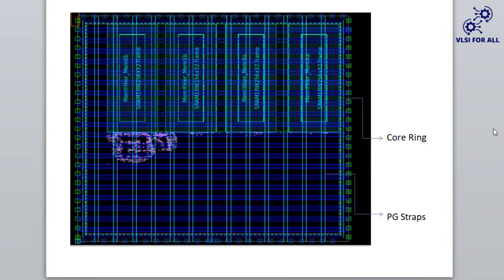The calculation depends on the power consumed by the chip, total current drawn, current rating of a power pad, current rating of metal layers, and the percentage of current flowing through the metal layers. Power distribution happens in three types: rings, stripes, and rails.